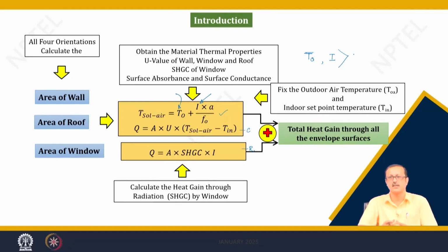And if the building is some other type of building, maybe a mall, it may work from morning 10 to a little late at night, maybe around 12 in the night or midnight, or if it is a hospital, then it works throughout the day. So, we have to see the total span of the working time, and based on that we need to take the outdoor temperature and the solar radiation.